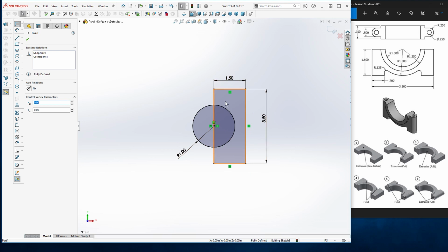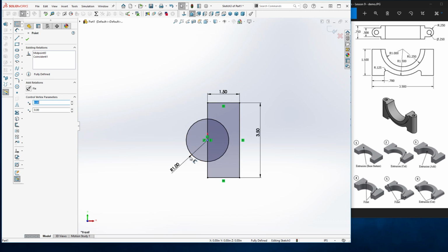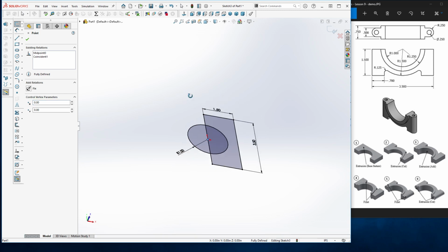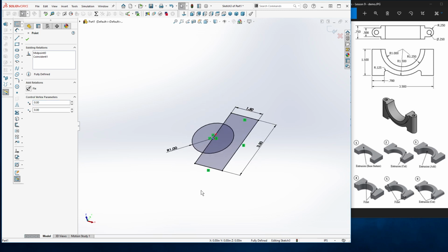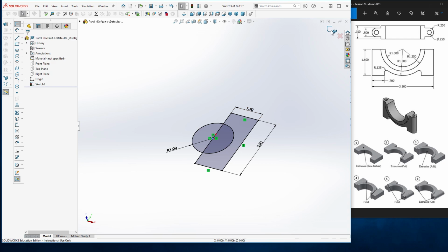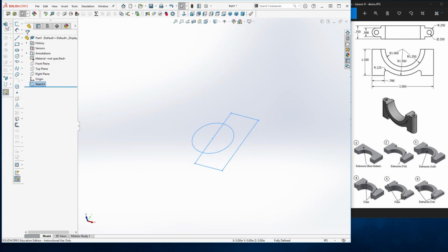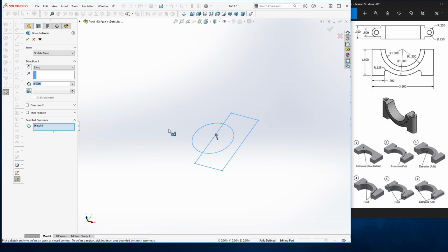So the next step is to do more cutting, but I want to show you one thing first. So I'm going to extrude this sketch. Now here is the X is the sketch. So when you're done with this sketch, you can extrude it in here. When I do the extrusion, I can select this portion only. You can do that in Inventor, but in this exercise I want to show you how to use relationship. So I'm going to trim this and then add relationship in here.